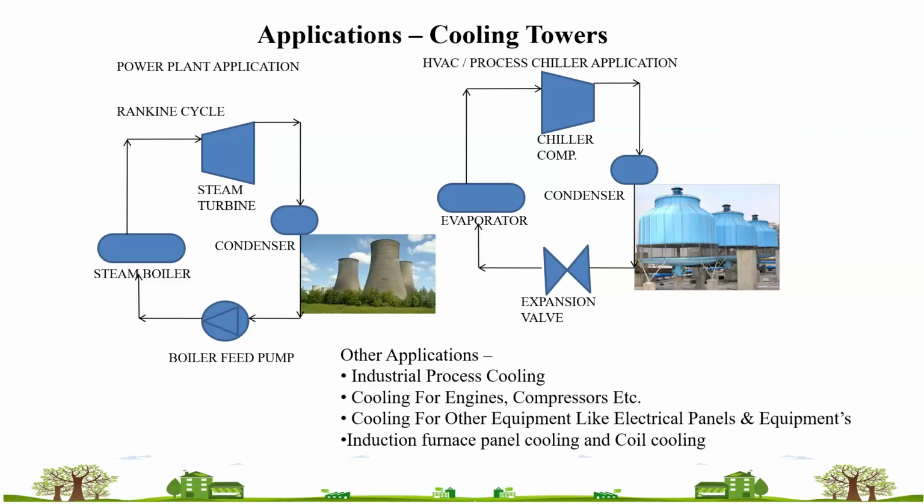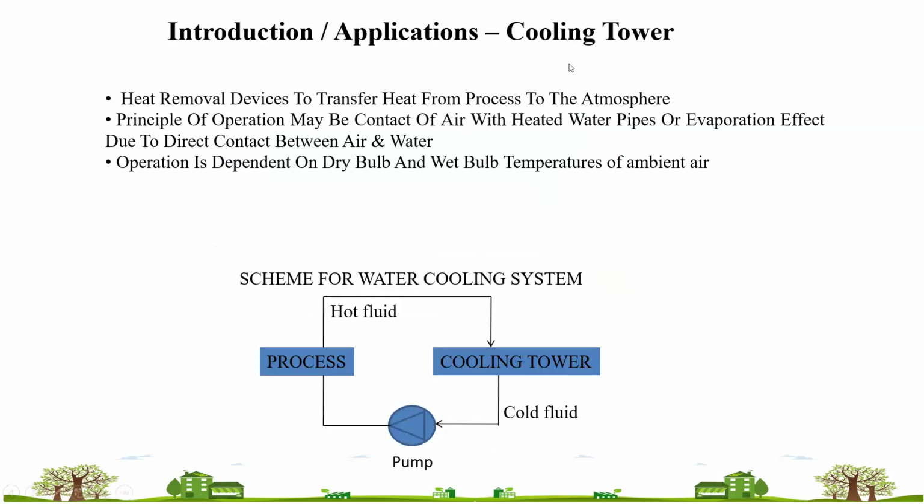So where your water is finely atomized, and it can get maximum surface area, and all the heat accumulated can be rejected to the atmosphere. So the main parameter deciding cooling tower performance is your ambient air. Ambient air means the conditions you are placing your cooling tower in, what kind of atmosphere you are providing to the cooling tower.